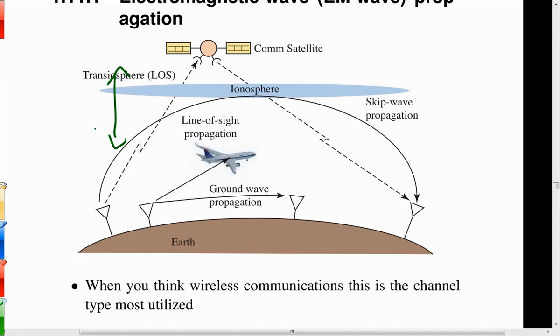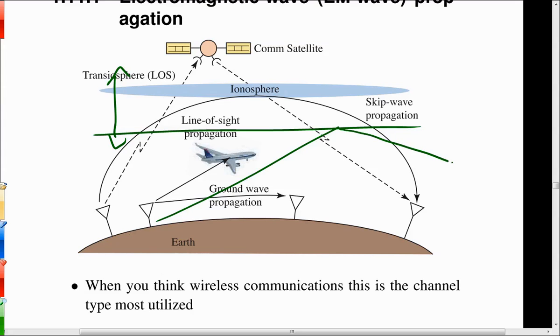If this layer was to come down, then a wave that bounces up, and angle of incidence equals angle of reflection, right? Then it's going to go a lot further than if it's up higher. It tends to just go up and come right back down again in the locale. So the reason why it might appear that AM radio doesn't work at night is because of this ducting, or this lowering of the ionosphere, which means that radio waves in low frequencies travel a huge distance.